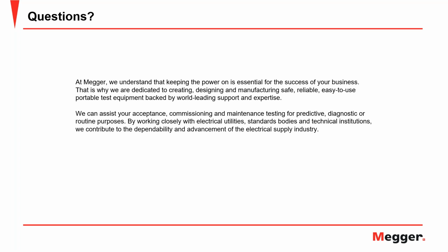All right, thank you. So, Ken, how can you correct the power factor for temperature if I don't have a Delta 4000 or the tracks? Can you suggest an alternative way? Sure. So the way that has been used for many, many years would be to look at what's called a temperature correction table. A temperature correction table is based off of, let's say, a transformer year, what kind of insulating liquid, what the rating is on the winding. These will get you in the general ballpark for a temperature correction value that you can use if you don't have the Delta 4000 or the tracks.